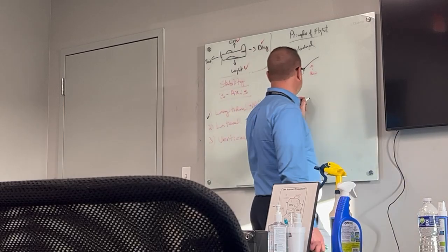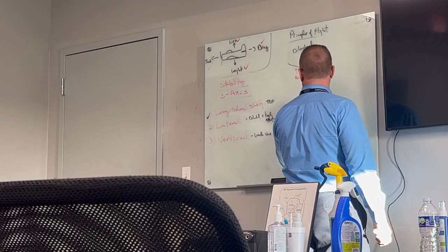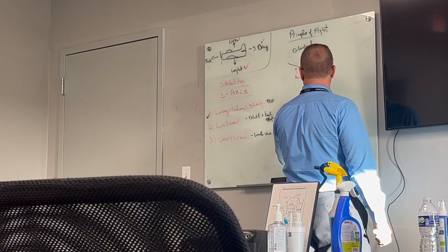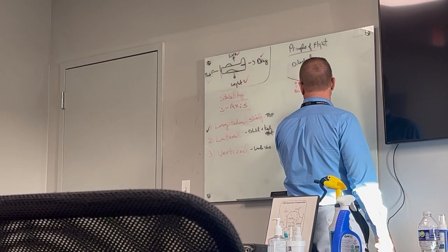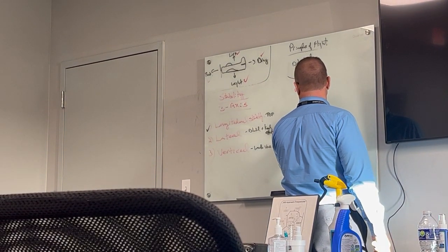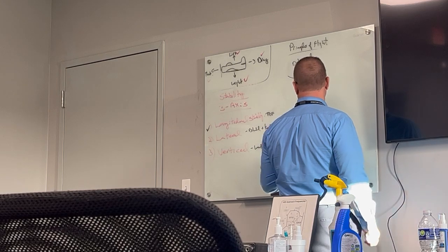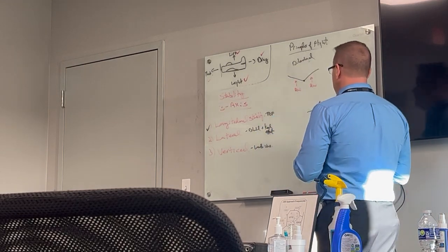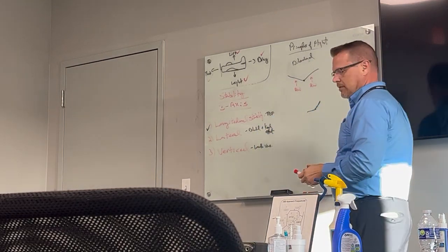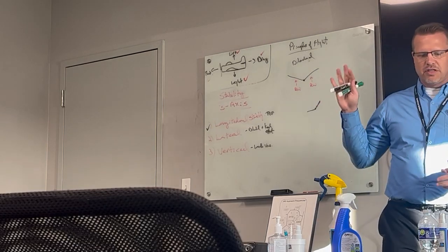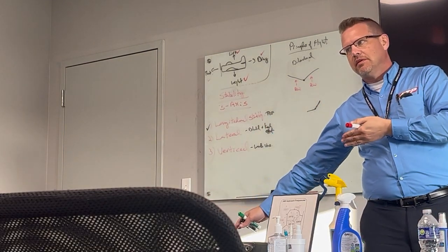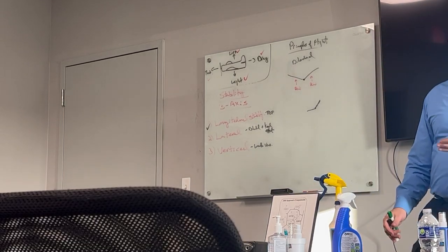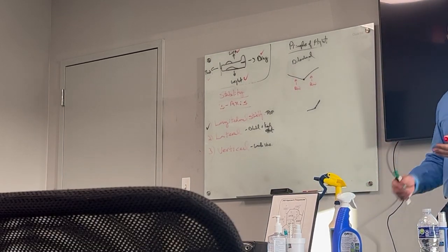So if our plane gets disturbed and it goes into a bank because of this disturbance, what's going to happen is, especially if it banks enough, the plane's going to end up slipping off in the direction in which it banked, or in the direction of the lower wing.